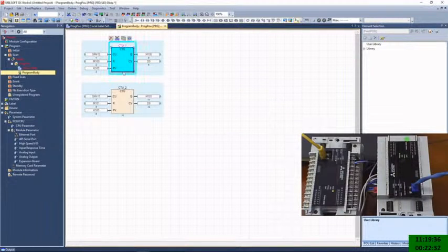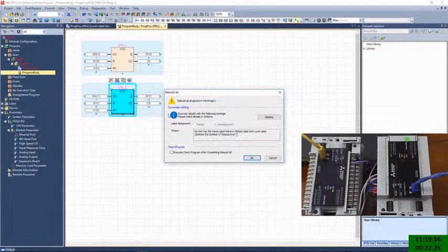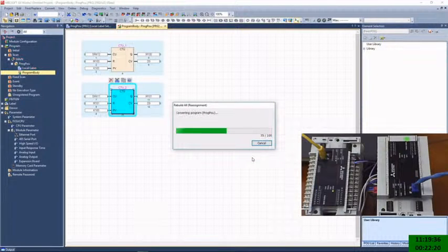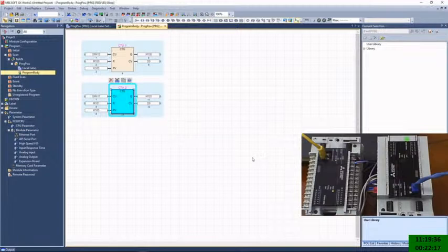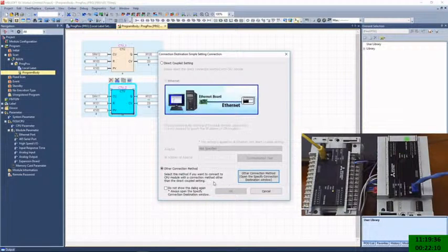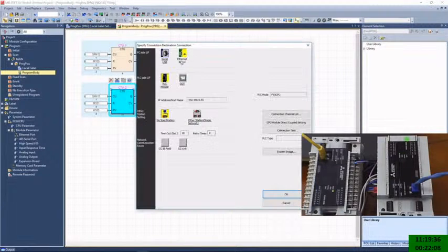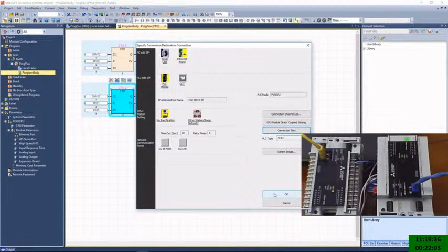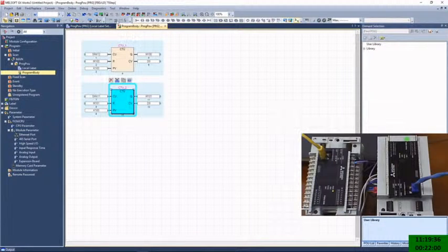It's just basically to create network data so that we can check if our network connections are actually working. Rebuild it, and that is your slave basically set up as quickly as that. Alright. So next step I say write to PLC, and first check my connection. Connection's fine, and then I would download the program to the PLC, which takes a few seconds.